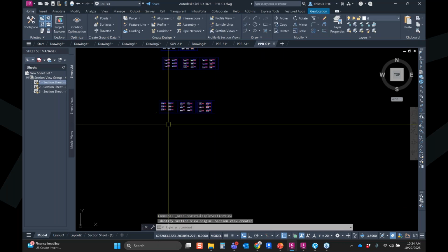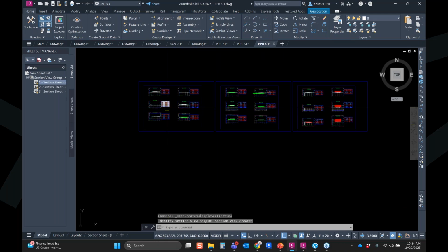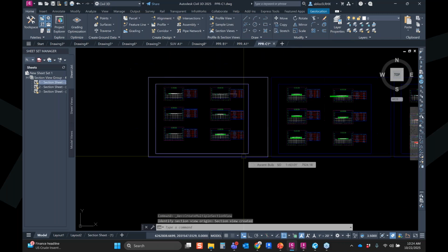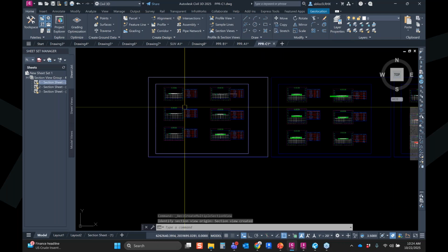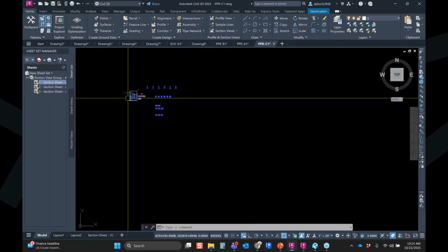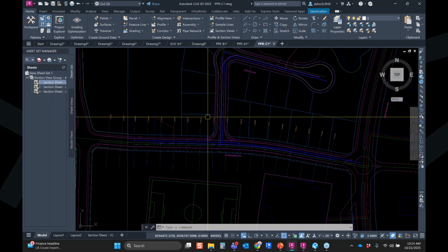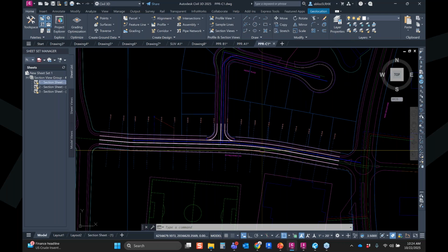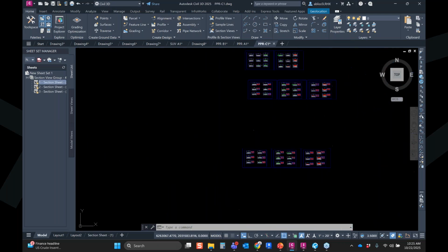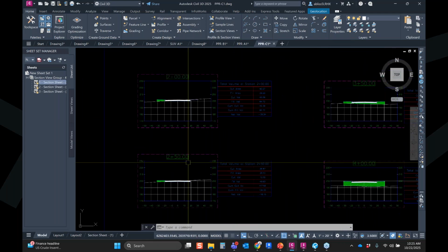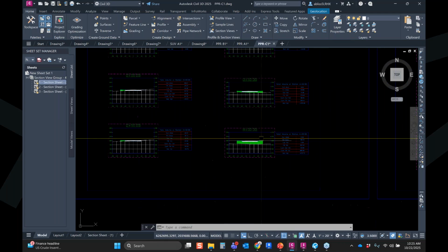All right. So here's the space for that template where it has the title block and the viewport and everything. And it drops those sections in every 50 feet, following my road over here with all of my sample lines running through. So every 50-foot station, it's got a new sample and a cross section. It's showing the cut and fill. As it goes by, you can see the color change for cut and fill.